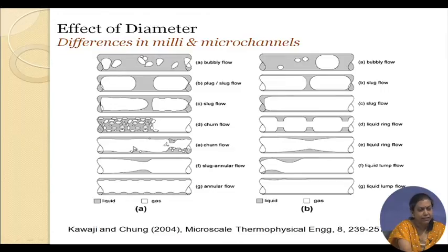There is another thing also which people call the churn flow pattern, which is when the gas plugs become quite large and they almost merge with each other, but we find that the gas core is marked by a periodic wave. It is this sort of a thing.